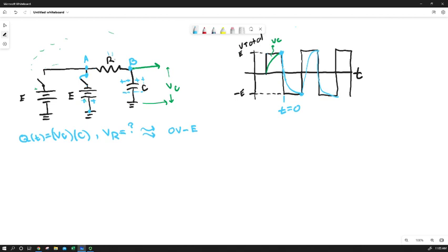As I go from A to B, I'm either going to add or subtract the voltage drop over the resistor. This is a bit like some of our network analysis, where we have to know which direction the current is flowing to know whether we're swimming upstream against the current, in which case we would have a voltage rise, or going downstream with it.